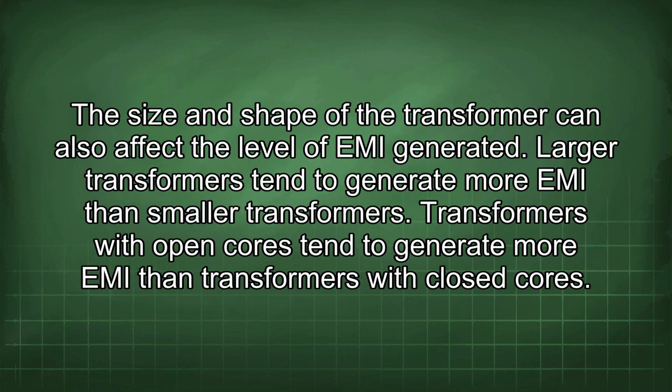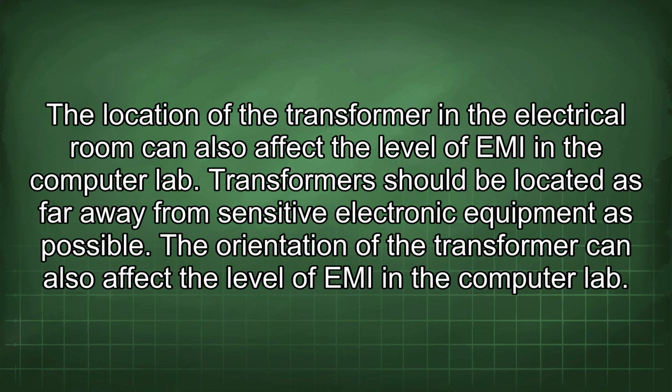The size and shape of the transformer can also affect the level of EMI generated. Larger transformers tend to generate more EMI than smaller transformers. Transformers with open cores tend to generate more EMI than transformers with closed cores. The location of the transformer in the electrical room can also affect the level of EMI in the computer lab. Transformers should be located as far away from sensitive electronic equipment as possible.